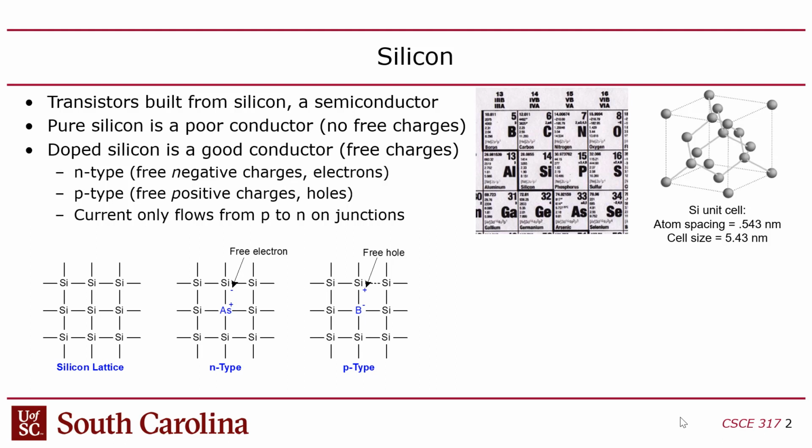So semiconductors are built from silicon, and silicon being a semiconductor, it means it does not conduct electricity very well, but you can make it conduct electricity by putting dopants in it. Silicon forms a crystal, a lattice, where the silicon atoms form covalent bonds with 4 neighboring atoms. And they form those bonds at certain angles to make this repeating crystal structure. The repeating pattern in a crystal is called a unit cell.